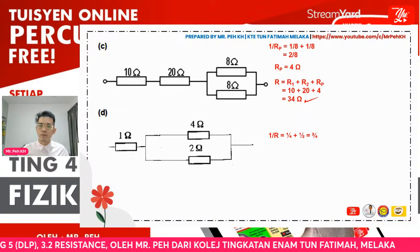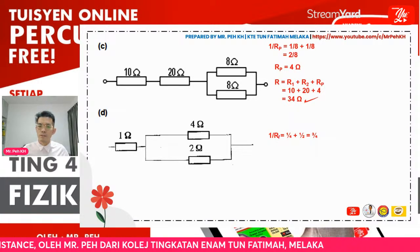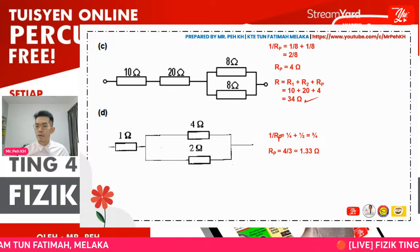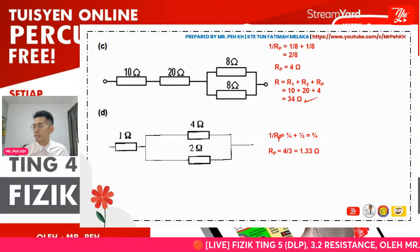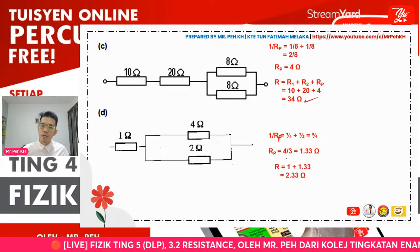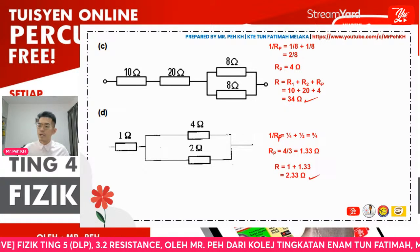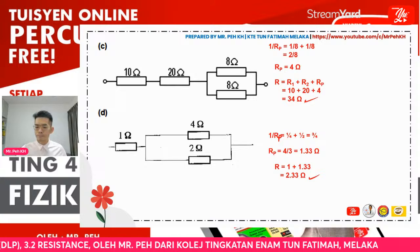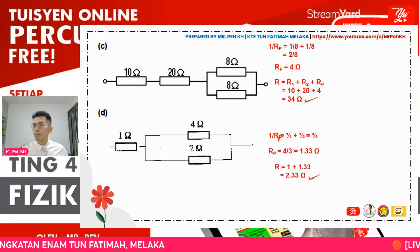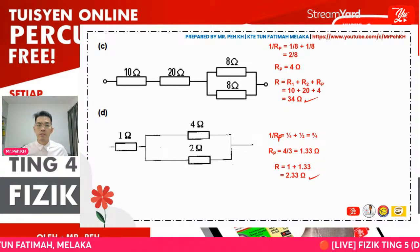Just now I showed you the first, the parallel parts, they will be 4/3. So you have to change to decimal place. You can leave your answer in fraction first, then end with decimal place. After that, you have to add both together. So you get 2.33 ohms. So that is the practice on how we calculate the effective resistance for different circuits.